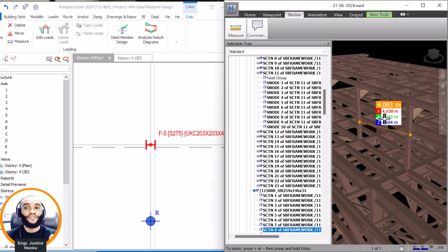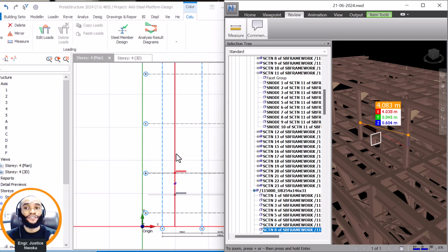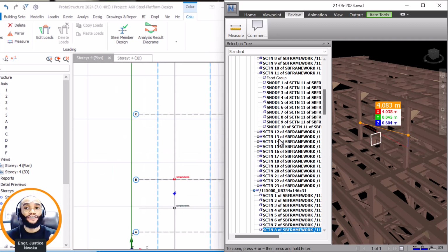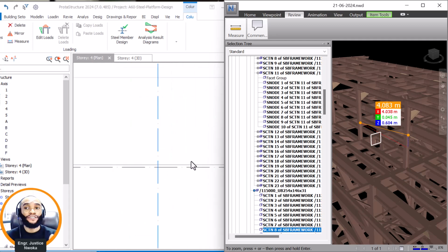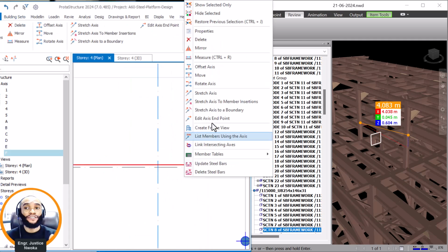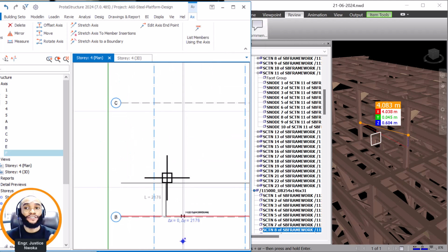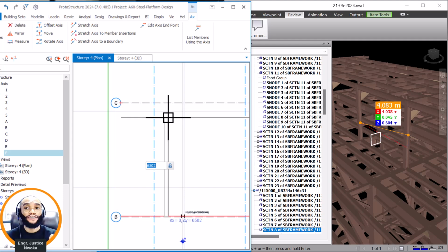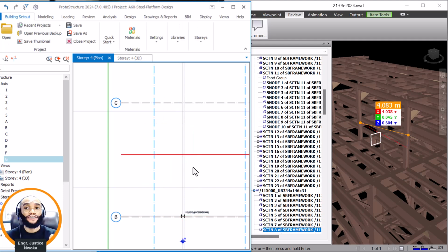4038. So we are going to use 4035 or 4040. Okay, for that. Now let's know where it's going to be. Okay, let's say 4040 millimeter. So I'm going to offset that right now. Click on this, right click here, then move offset 4040. Let's see if you switch with hit heads here. No, so we're going to shift right now, F2 4040, and then enter. That's fine. So the next column now is going to be here.